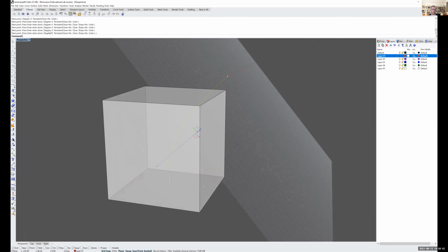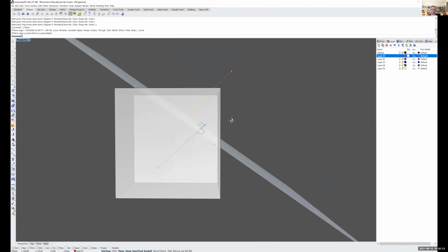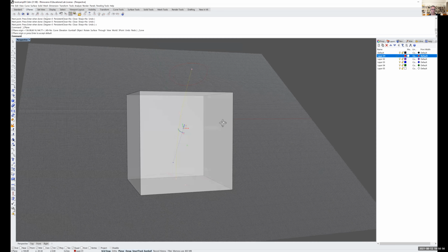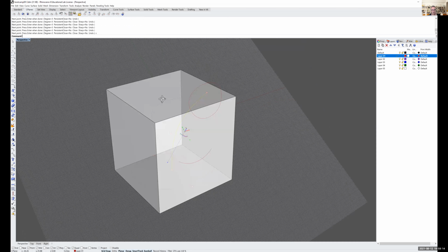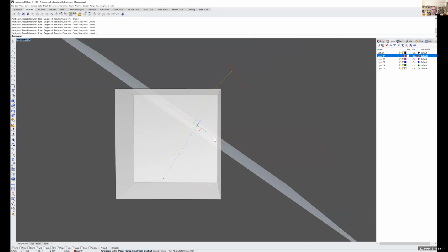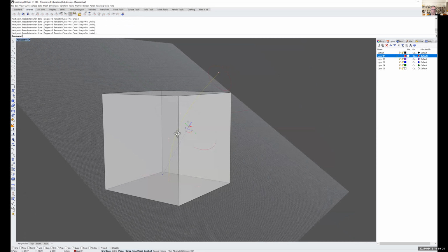The next one that I want to do is move that C-plane, again using perpendicular to curve, to somewhere along the middle of the curve. That way we can just draw a third shape. Fourth, fifth, sixth, however many we want, but we'll just do 3 simple shapes. And try not to snap to anything. And if you do end up snapping to something, we can disable the snaps so that it doesn't override anything. Because in the end, we want that shape to be flat on that construction plane.